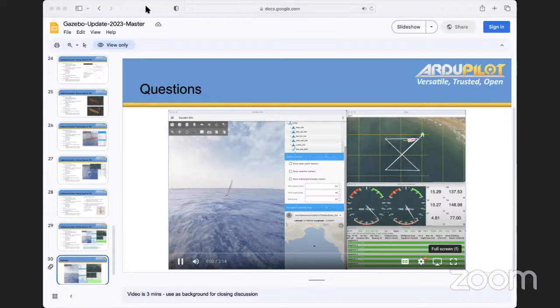So I wanted to ask about the camera APIs, like how do you access the camera on, say, a Python script? Okay, so he wants to ask about the relaying of cameras via Gazebo. So can we get input from camera systems? I'm guessing computer vision type applications. If you wanted to do visual odometry or avoidance applications, how would you pipe through the video data to be able to process those with a Python script at some point?